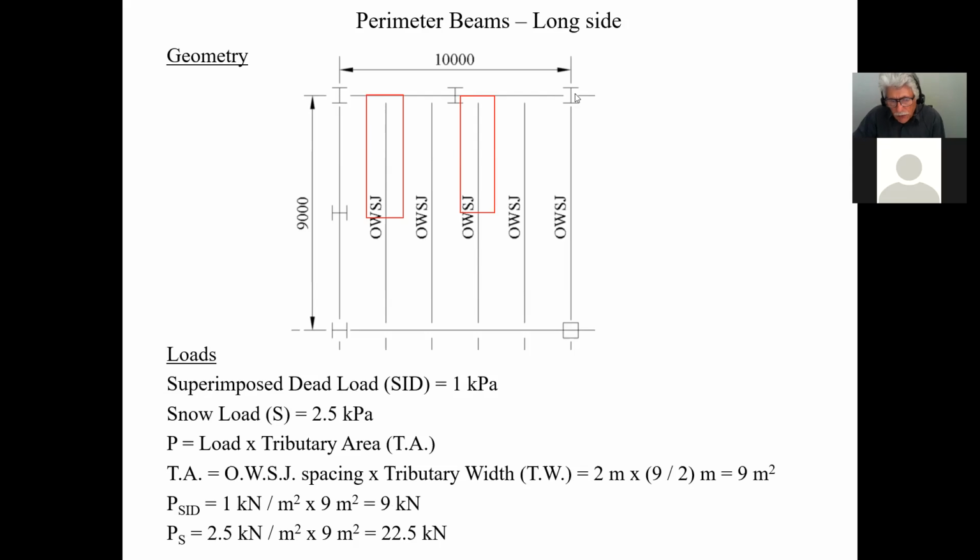And of course, I always use the service loads or the specified load. And then in the load combination is where I modify the load factors and be able to get my design load. So with ADA, you always use your specified loads, and in the combinations, you make sure that you use the appropriate factors. So this would be multiplied by 1.25. This would be multiplied by 1.5. In other words, this is load combination number 3.